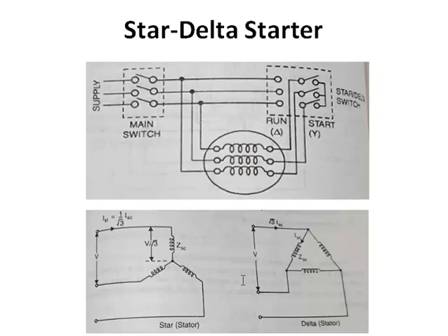The reason for that is, when we have the star connection, for each winding the phase voltage, whatever the voltage that is applied, would be V divided by root 3. This means the voltage applied to each of the windings gets reduced by V divided by root 3. This is during the starting. Once the machine picks up speed and starts running, it will be given the full voltage.